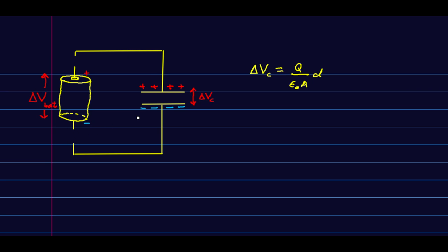Well, remember, these charges are here, and if we've used, say, rubber gloves to remove these connections so no charge could flow out through us, then this charge is trapped here. And so even though we've disconnected it from the battery, there's still this charge on the plates. It can't go anywhere, and so there's still a potential difference across the capacitor, even though it's no longer connected to the battery.